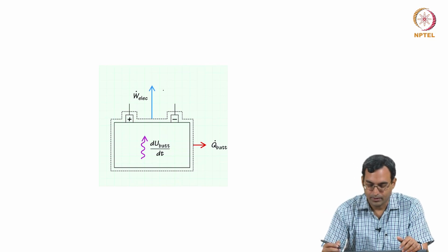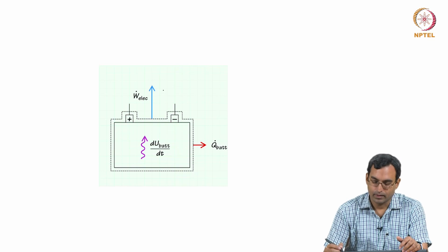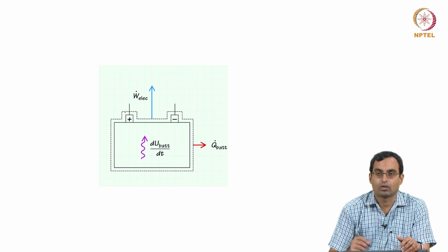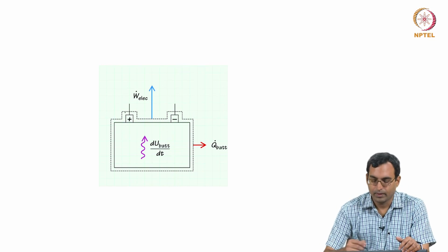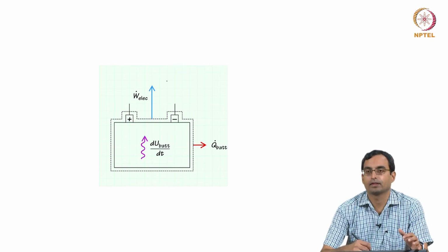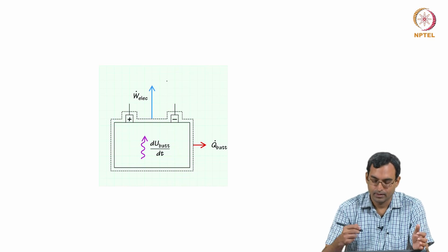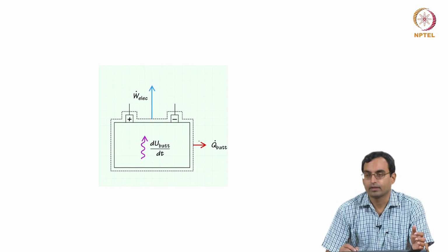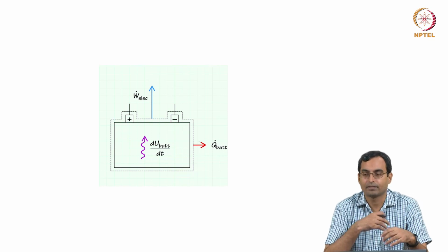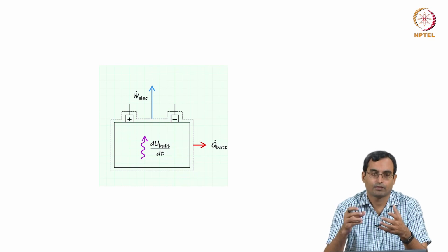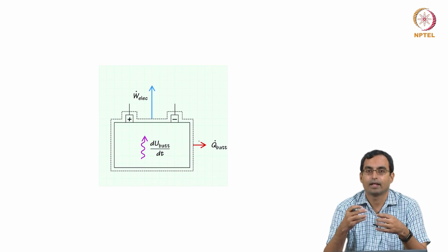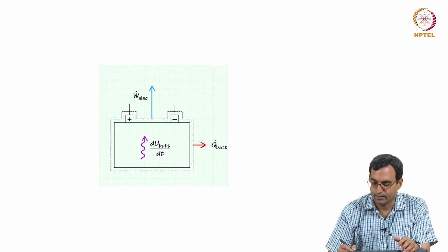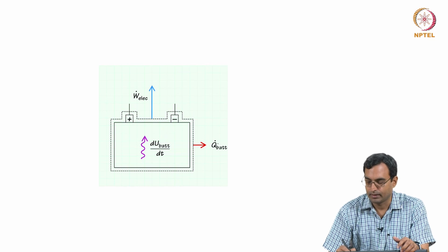But now if you look at the battery itself, we have this battery over here. So, let us take the control volume as this drawn just around the battery. So, we have electrical work which is going out because there is current being pushed out of this battery. So, we have W dot. If there is any heat transfer, which usually happens, for example, you have a mobile phone, you keep it on for a while, let us say you are doing something demanding on it, it becomes a little warm, the battery as it discharges releases some heat. So, then that would also be Q dot.